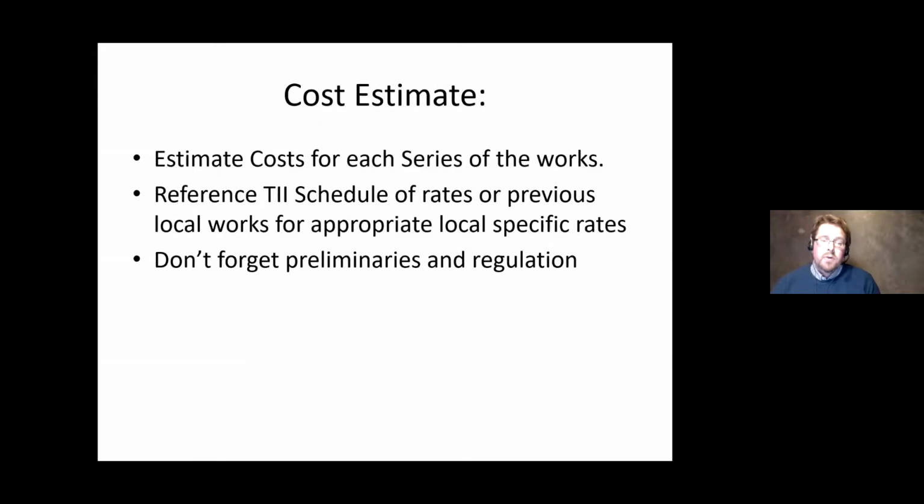If you've gotten previous works done in the area, you'll know what your rough costs are for a particular aspect of work, so use that cost as well if you can back it up. If you're like ourselves in Westmeath, Offaly and Longford have developed a framework of contractors to work in the area, so as part of that they also got a draft tender of different costs, so based on that you can have an idea of what it's going to cost to get certain work done in certain counties. And again, at this point as well, don't forget to put in a cost for your preliminaries, and don't forget a cost for your regulation, because if you forget regulation, you will get hammered.